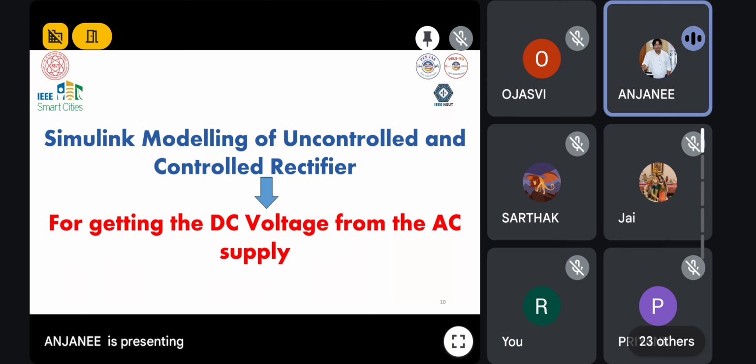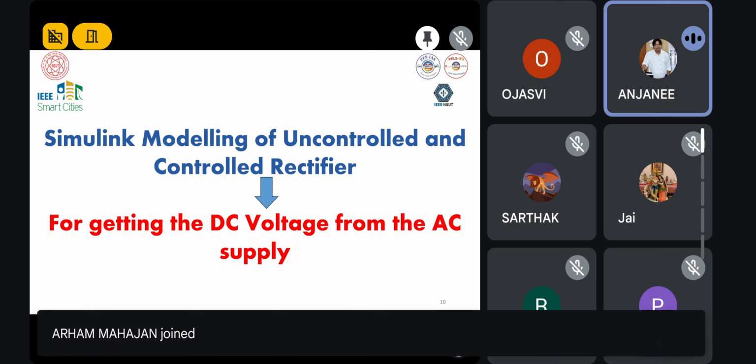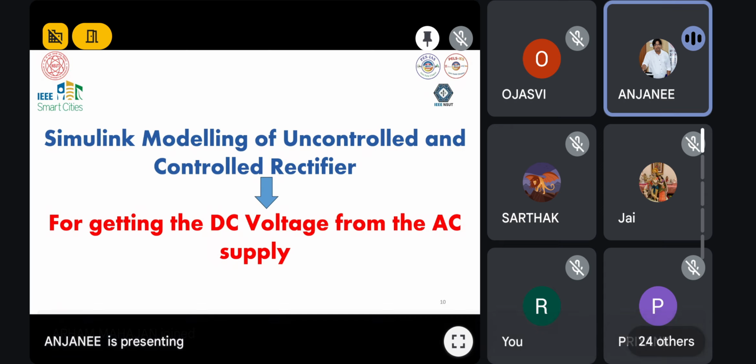So there is also need of a controlled system, not only the uncontrolled one. Because as you all know, the output of the uncontrolled rectifier is 2Vm upon pi, where Vm is the peak of the coming AC voltage, root 2 times the RMS. Like if 220 or 230 is coming, then 220 or 230 into root 2 divided by 3.14 and into 2, that is 2Vm by pi.